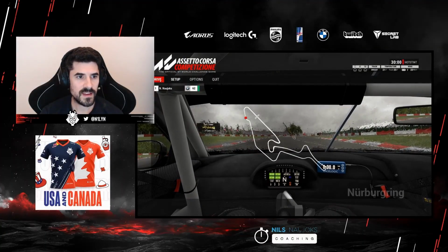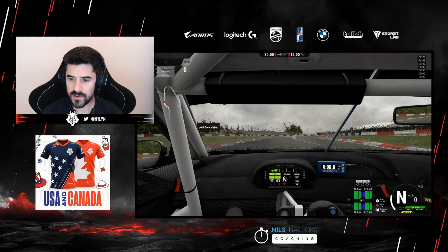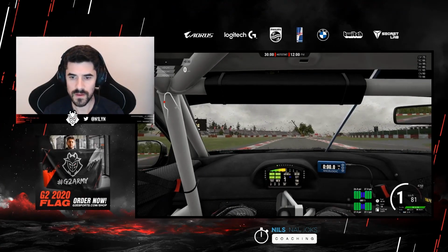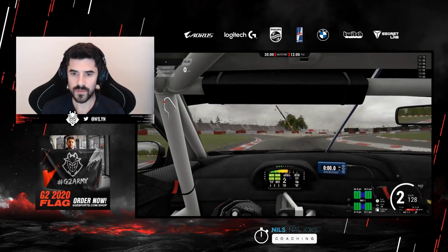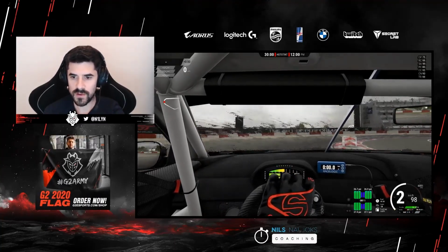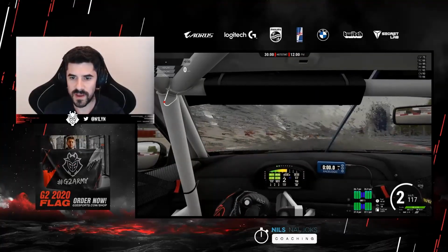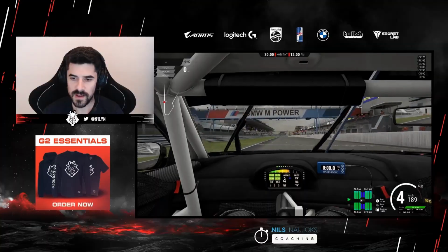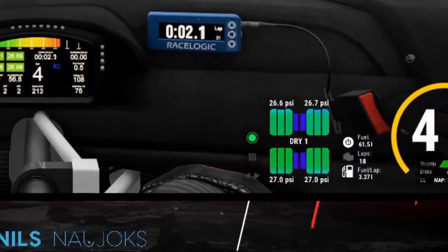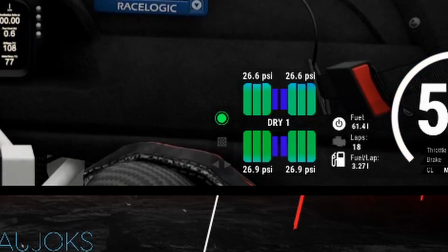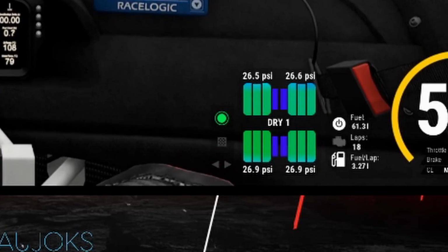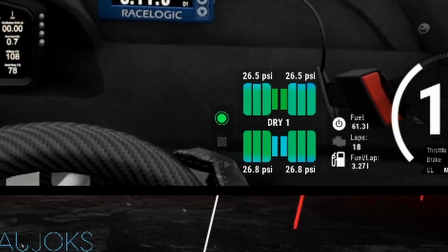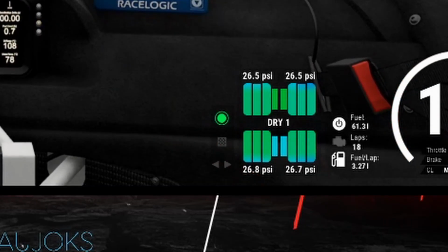Now, taking the dry tire in absolutely equal conditions. We still had an optimum track a second ago. Now it started raining and it's starting to become greasy before it's becoming damp. The dry tire is still kind of working, but you can see the surface of the tire is already turning light blue, which means it seems like the tire will not be able to generate the necessary friction and therefore not the necessary temperature, and it will cool out.